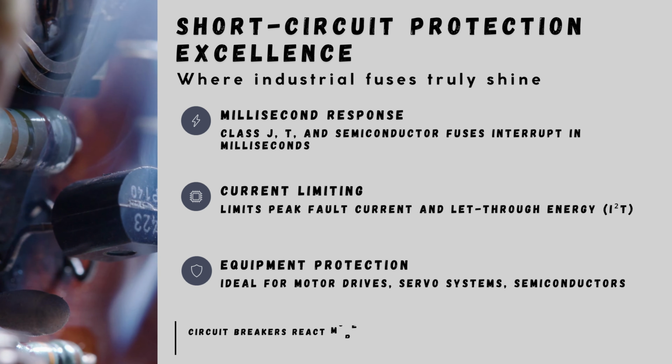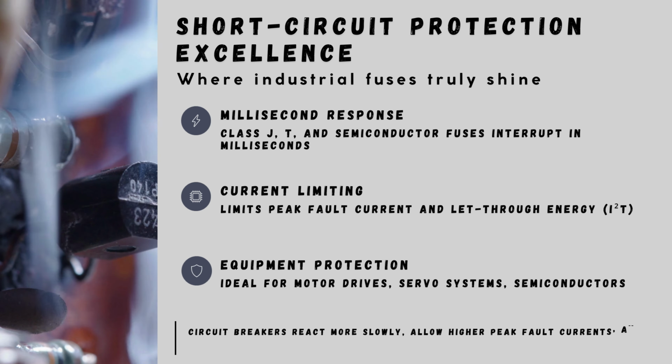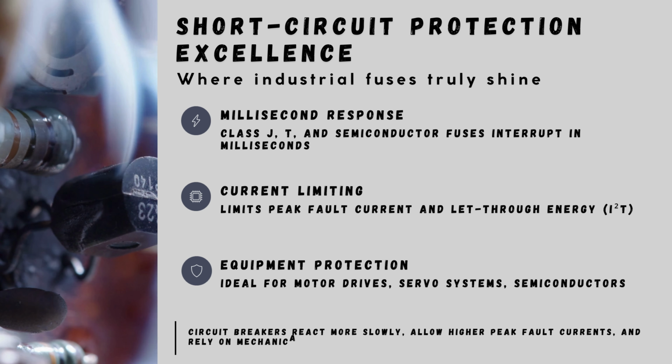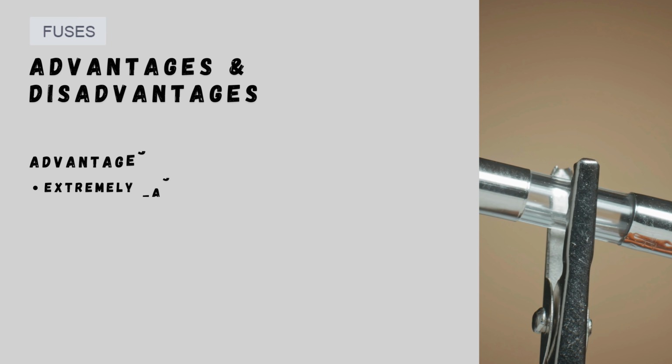Circuit breakers also provide short-circuit protection, but they react more slowly, allow higher peak fault currents, and rely on mechanical movement, which introduces delay. In high-fault environments, fuses often provide superior equipment protection.